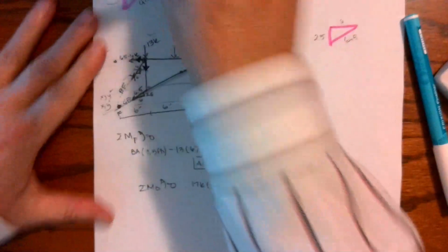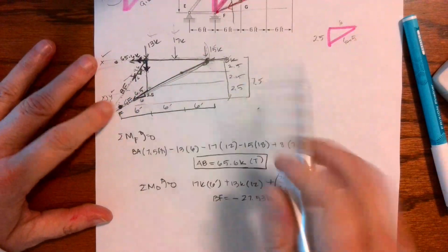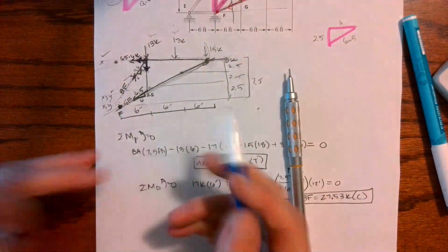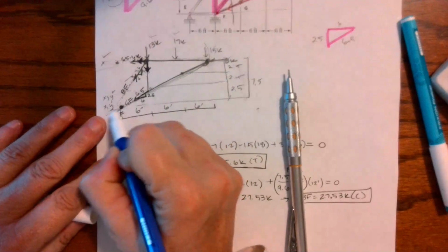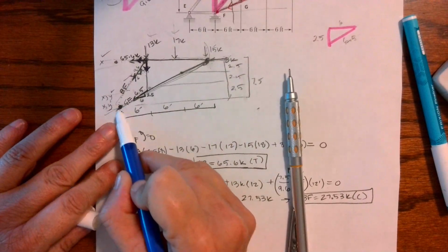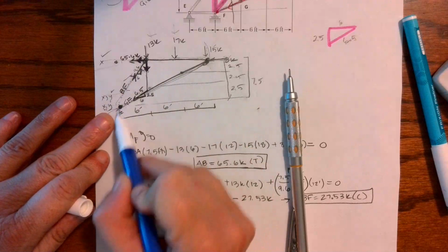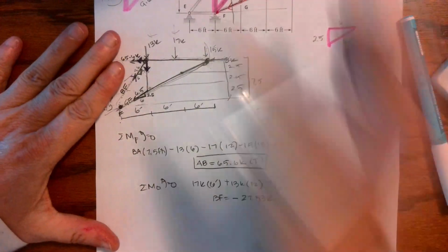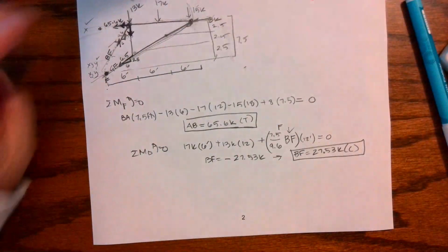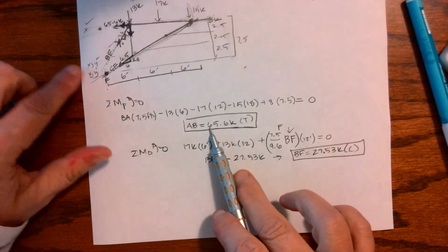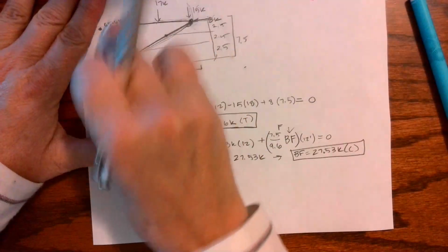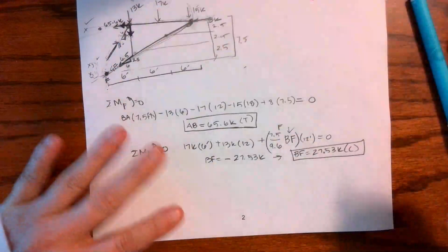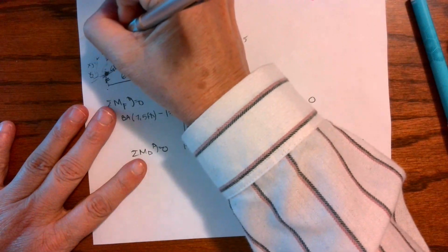If I wanted to, I could have come down here and drawn the same arrows anywhere I wanted. But even if I was down here, I would have had to include the X component and the Y component as I came down. That's more math. I want to go where I've deleted everything. So I now have AB and BF, and I know that BF is actually in compression, so I'm going to draw it in compression, and it's 27.53.